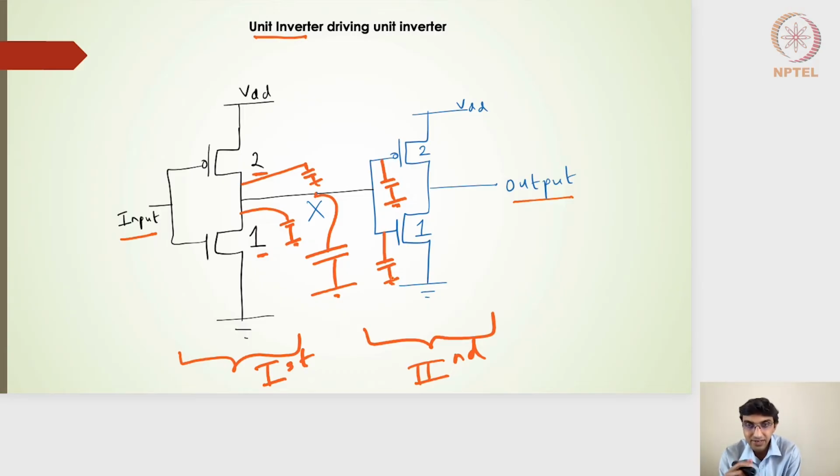So once I have these capacitances, then I should be able to estimate what the switching resistance of this PMOS transistor should be, and then what the switching resistance of the NMOS transistor should be. And we know that the falling and rising resistances, that is the switching resistances, for a 2:1 unit inverter are the same. Right? So if the switching resistance of an NMOS in a long channel model is around 560 ohms, then for a width of 2 times the unit PMOS, the PMOS transistor will also have a switching resistance of 560 ohms.